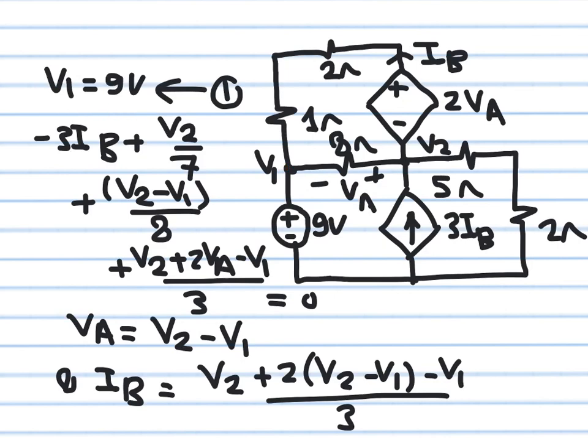Okay, so I managed to get one equation from that node. Now for the second equation, can I apply KCL here? Someone will say, no, there is a voltage source connected here and I cannot apply it. No, you can apply KCL. Why? Because of the change that happened in the topology of the circuit after we remove that branch, this voltage source has a resistance in series.